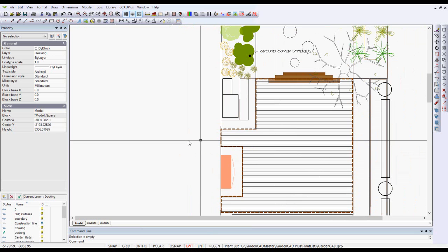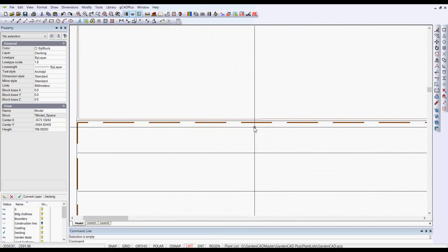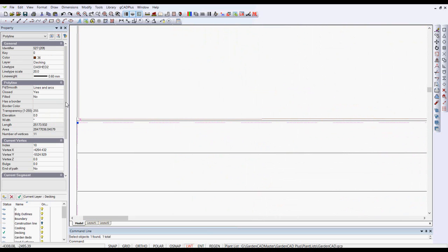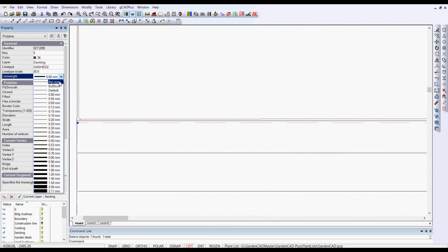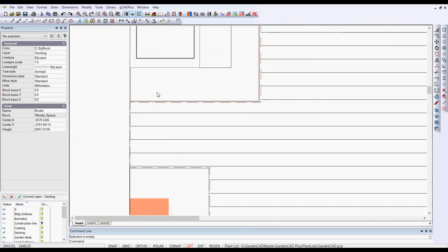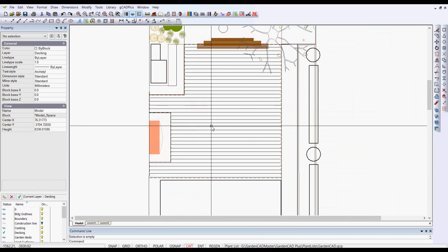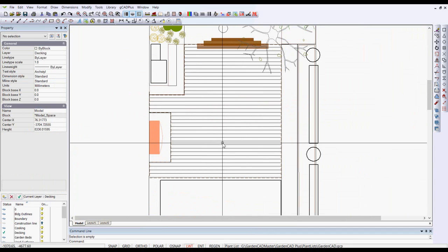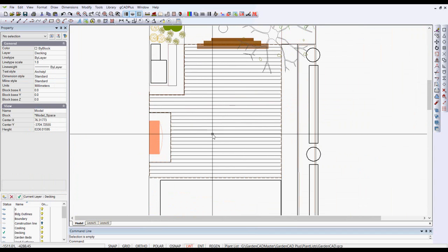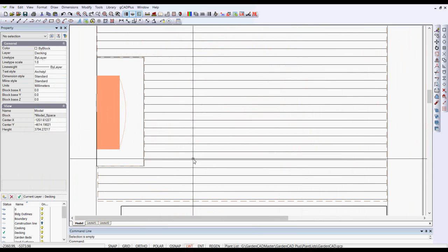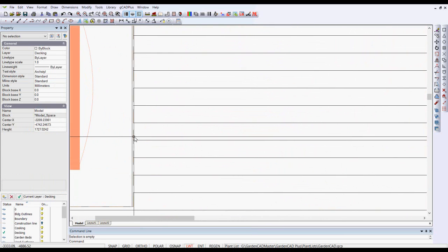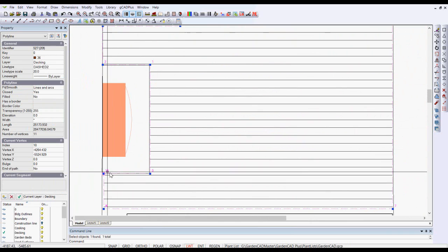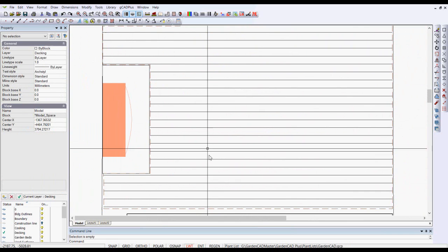I'm not sure now that we need a heavy pattern, so let's put it to our preferred state and pick BYLAYER. So there's our dash line showing around there, so we hope that that's what the drafter had in mind here. Just want to select it again and just check how it moves through that area.